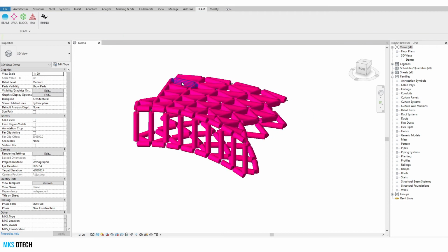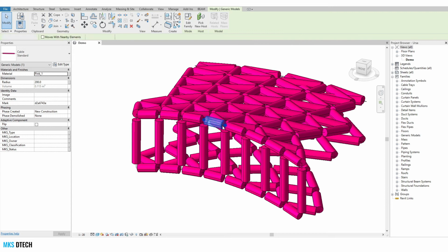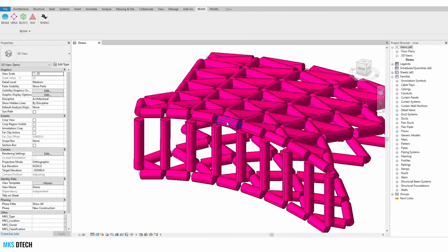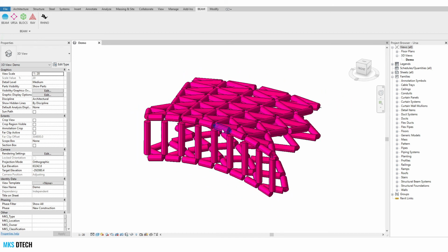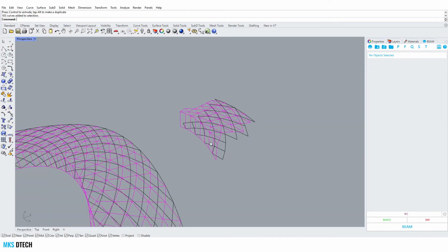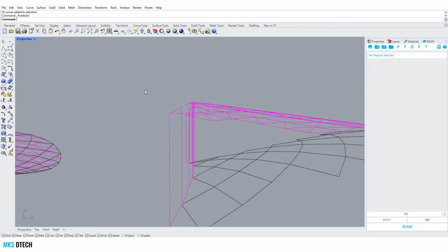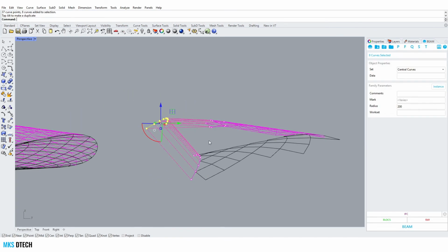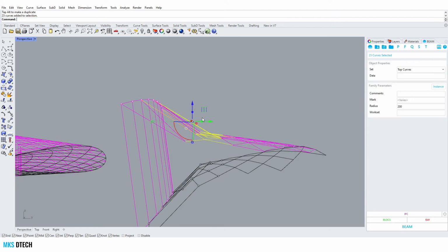Now, we all know that in Revit, it's always difficult to manage the design. So in case I want to change the points, or I want to change the design of this roof, it's a bit complicated because I don't have a proper gumball like in Rhino. So it's always important that you do your design changes here in Rhino, because it's faster and easier. So in this case, I can change my geometry like this, in case I want to update my design.